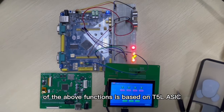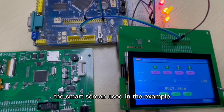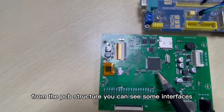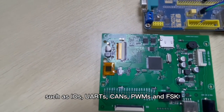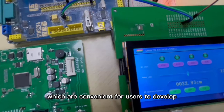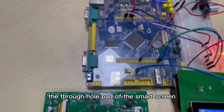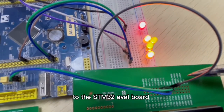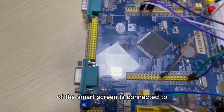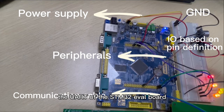The development of the above functions is based on T5L ASIC. The smart screen used in the example belongs to EKT evaluation board series. From the PCB structure, you can see some interfaces such as I/Os, UARTs, CANs, PWMs, and FSK, which are convenient for users to develop. The wiring of the example is to connect the through-hole pad of the smart screen to the STM32 board with dual-bond wires, while the UART2 of the smart screen is connected to the UART of the STM32 board. The wiring diagram is as shown.